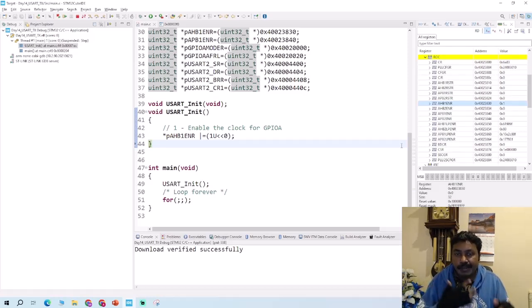So as a matter of rule, in the learning coding stage, when you try to change the bits, try to match that with the register. Go into the register and see, by using step into instead of full resume, and if you click that, then you will see for yourself whether you made that bit 0 or 1. So we asked for the bit to be 1, so that's what it's showing, enabling the clock.